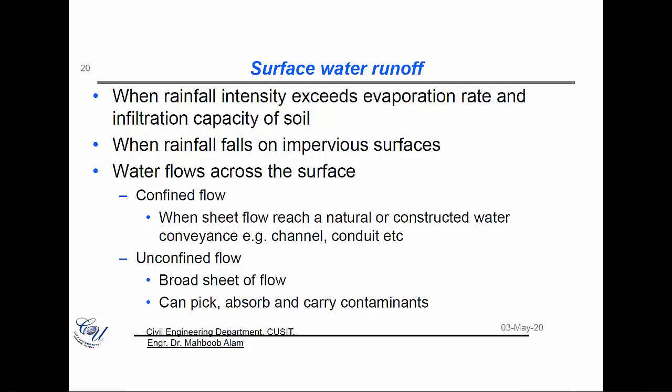And basically we usually define the flood situation as when runoff or rainfall is more than the infiltration capacity of the soil, and it also exceeds the evaporation rate. So water is coming down, less water is going up in terms of evaporation, less water is infiltrating into the soil because of, let's say, the intensity of rainfall. And if these situations are there, then the flooding situation would be there.